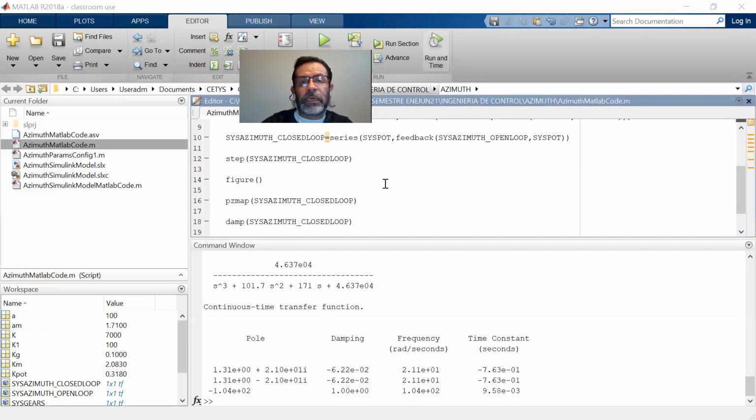Look at the dampening ratio. The dampening ratio is negative. Why? Because instead of pushing the signal down, it's making it larger. So a dampening ratio that's negative, as I think Luis said, is going to generate a response that I don't want. It's going to generate a negative type of response that's going to, by default, be unstable.